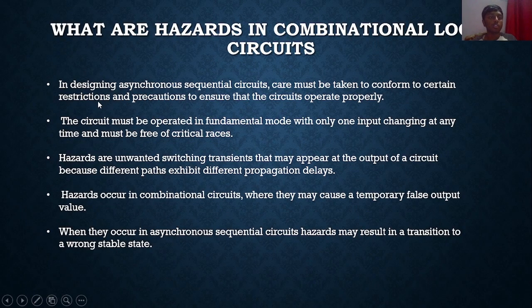Coming on to hazards, when we are designing asynchronous sequential circuits, certain care, restrictions and precautions must be taken so that the circuits operate properly. The circuit must be operated in a fundamental mode with only one input changing at any given time and must be free of critical races.